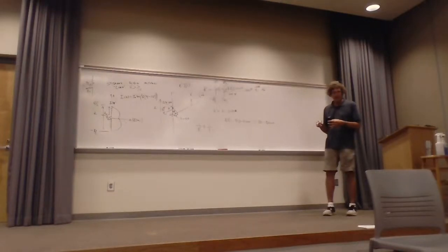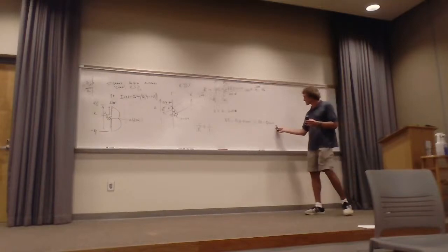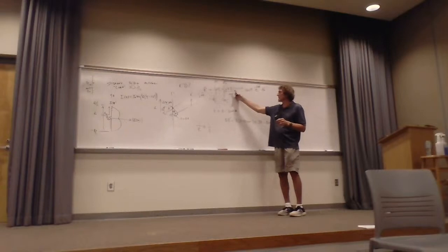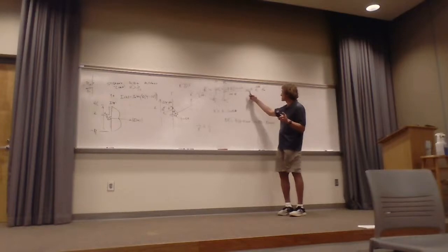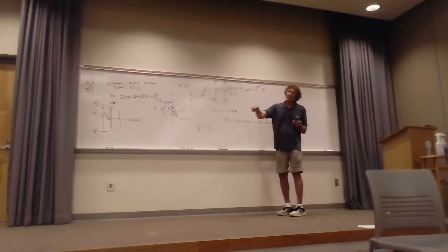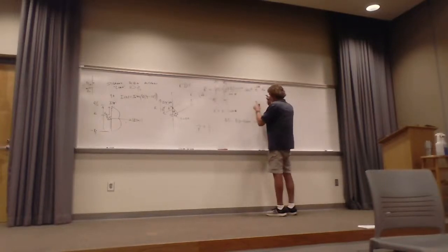Okay? Now here's what I'm about to do. If you're all with me, I'm going to take this quantity and stick it up there for beta R prime. But I'm going to do one other thing. I'm also going to factor out the j eta beta over 4 pi R, because R now is like a constant, because I'm integrating dz. It doesn't change versus theta. So I take that out in front. I can take the sine theta out in front, because that angle is going to be assumed constant, all right? But I'm going to leave in the I of Z business.